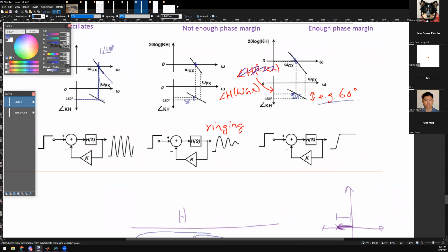As components age, as your car ages, as your rocket ages, as your satellite ages across decades, typically the phase margin tends to decrease, but within like 5 years it still goes down to like 40 or 50 degrees, and that's still more than stable. That's why industry makes 60 degrees, a margin up by design. If you have a project that has a long lifetime, you typically will see 60. If you have a consumer product like your phone, which is supposed to be disposed of in a year or two, 40 to 45 to 55 degrees is accepted in industry.